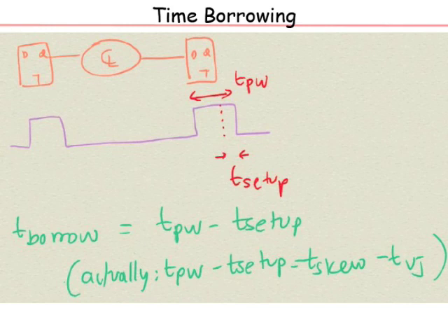Dotted line, no, because in this it's a positive transparent. So when clock is high, it's transparent. Clock is low, it is opaque. Actually, in that time the data should be available. If it is not available, then the extra time of the clock will be used for transmission. That whole time should be the data.